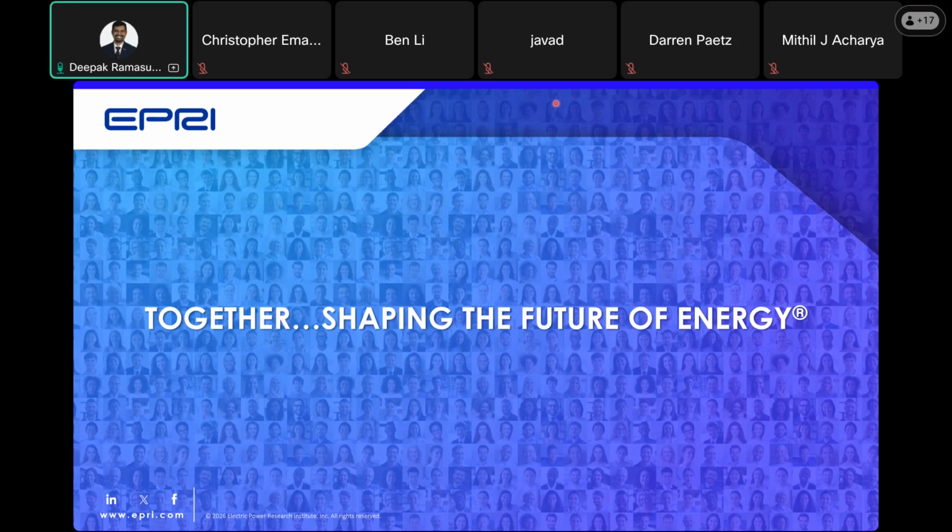In fact, this is a good pointer towards the part 2 webinar that we will be having, which will look at how, as you have different inverters in the system providing different levels of services, the megawatt percentage of grid forming that is required actually changes. You can go anywhere from saying you need 50% of the resources to be grid forming to maybe only 5%, because it all depends upon how much capability and services we get from the other resources in the network.